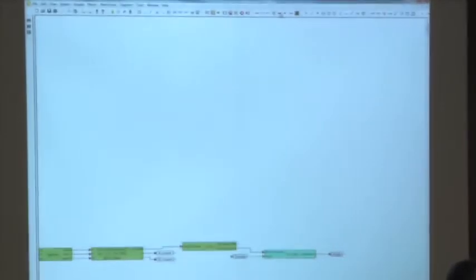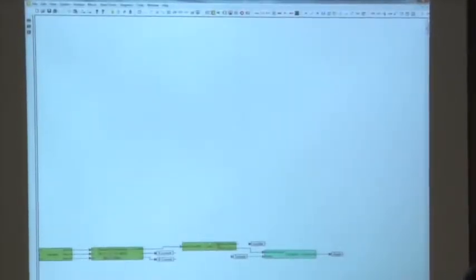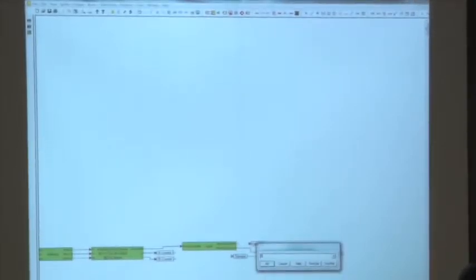I'm going to go up to the VAR tool, create another variable, put it on the output of the load block right next to the shaft speed. I'm going to call that variable something creative like speed. And then connect it up to the load block. Okay, where does that speed feedback need to go?